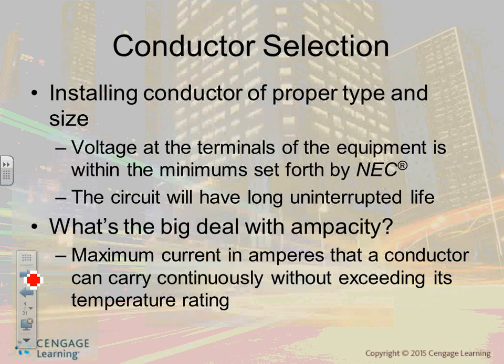Make the white identified red? Yes, white, red, or black. Typically black, or you can identify it as red too. If you're using the white conductor other than as the grounded conductor, which is the neutral, you must identify it, and there are rules for using it.